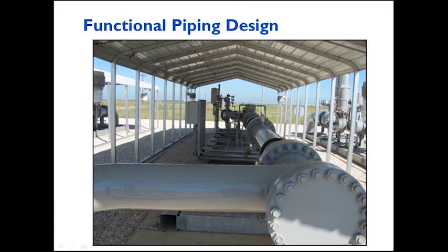And in fact, here is an example of an installation where we have an ultrasonic meter. We have the look-in tees on the ends. We could call those clean-out tees. That's a similar term. We have a connecting pipe to an elbow, a lateral turn through block valves on either end, or perhaps a tube switching control valve.